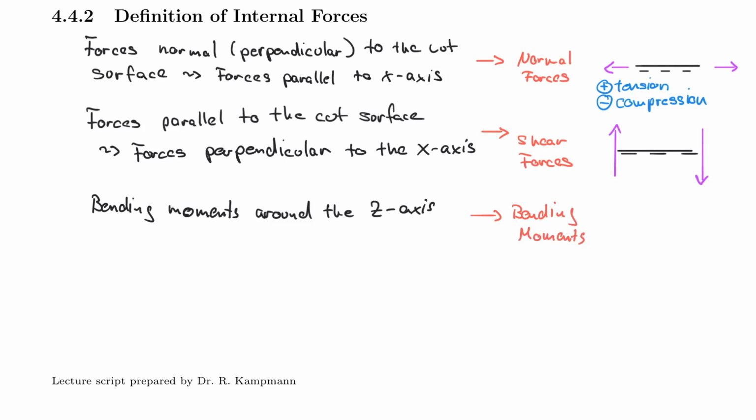And the way we identify those is really with the semicircles that rotate on one side in one direction and on the other side in the other direction. And mathematically correct would be to have them rotate this way around. Now, why does it make sense? So this is very important in the context of the reference fiber. The way I look at this is that these create positive bending. And what is positive bending? Positive bending is really elongation of the reference fiber. What do I mean by that?